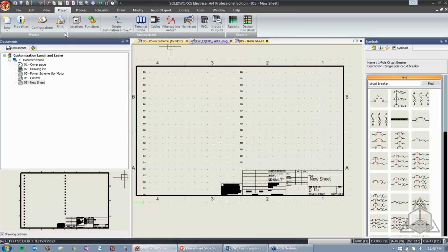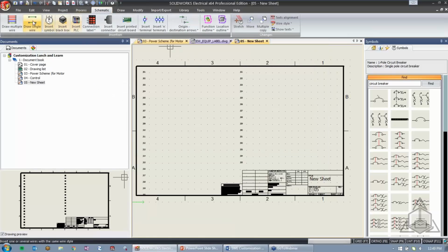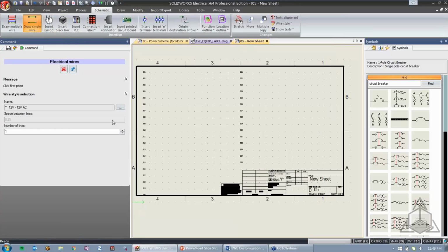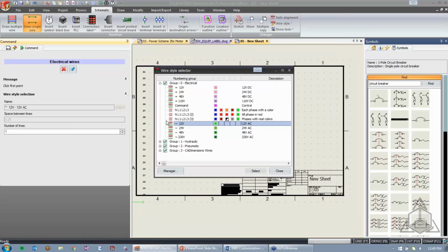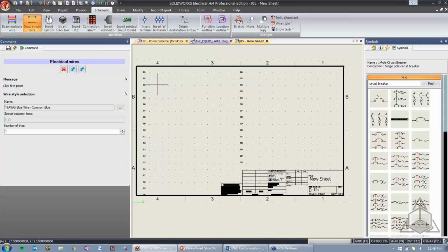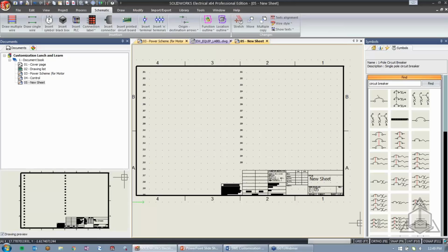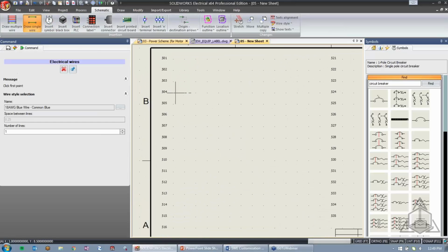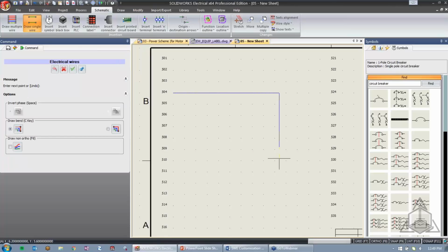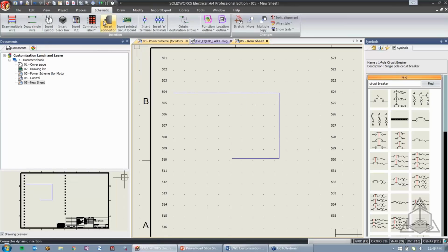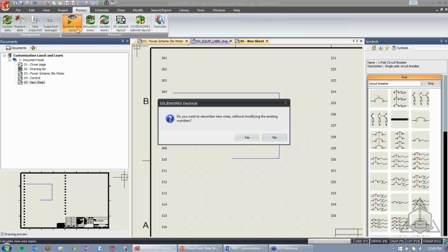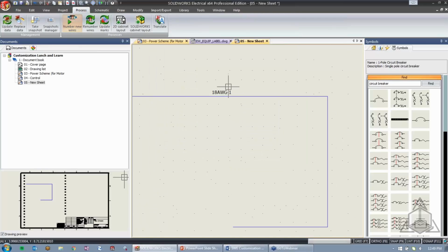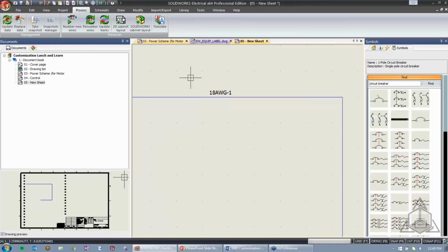So now that I want to draw this wire type, go ahead and draw a single wire type. I'll go ahead and find it inside of group 3, select it, and now I can draw. Oops, turn my snap settings on. Okay, that looks okay. So I'll draw a single wire type on this row. And under my process tab, I can number new wires. And what that's going to do is grab that numbering scheme that I created for that single wire type.